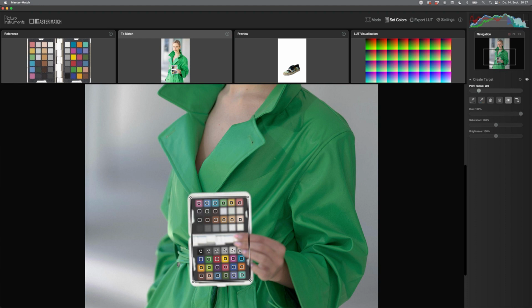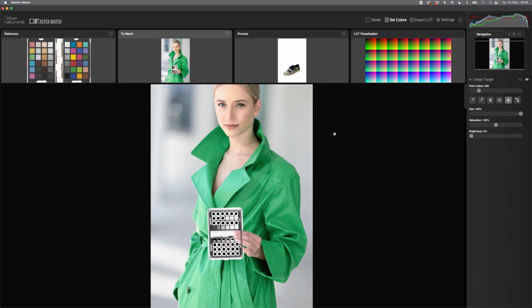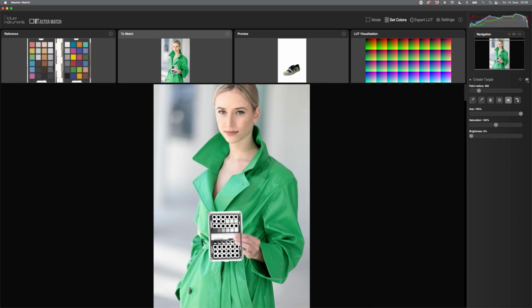Maybe I want to show you another thing. If you want to go with the neutral or with the spectrometer version, maybe I load this again, and it looks a little bit not so colorful, maybe a little bit lower in contrast, the brightness is different, and so on. So next to modifying the single points, by removing them, you can also modify the impact of the hue, the impact of the saturation, and the impact of the brightness of every single point. So if you go there and mark one point, you can change the saturation difference of this point.